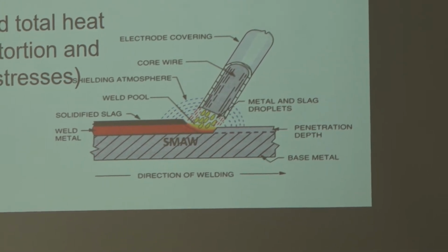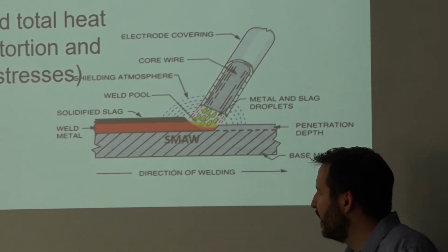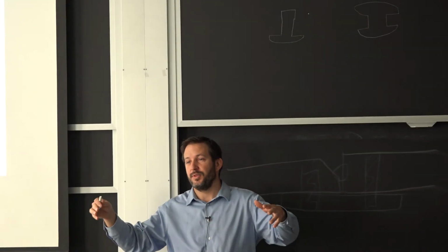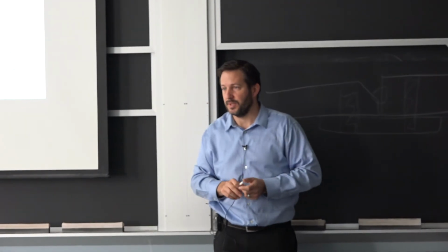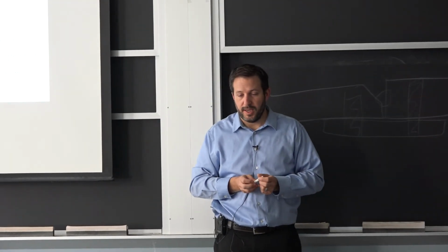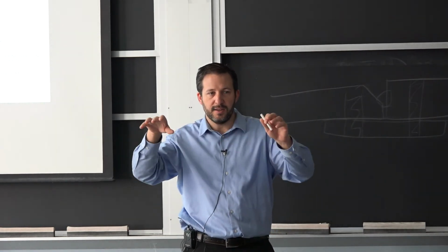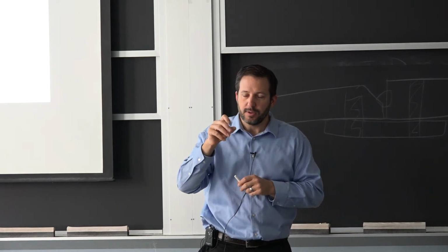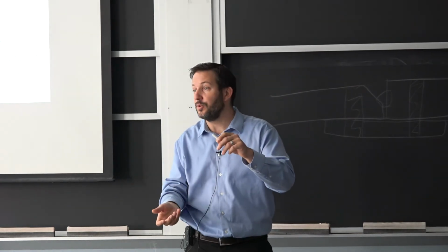So let's say it has been kept dry. What happens is it also melts and becomes a slag. And what a slag does with respect to the steels, first of all, it really is a blanket. So now the liquid steel doesn't see directly the oxygen from the atmosphere. But the other aspect, it has a cleaning power. So you have liquid steel in contact with essentially a floating slurry on top, and there is a thermodynamic force for that. That slurry is designed so it will grab on impurities.